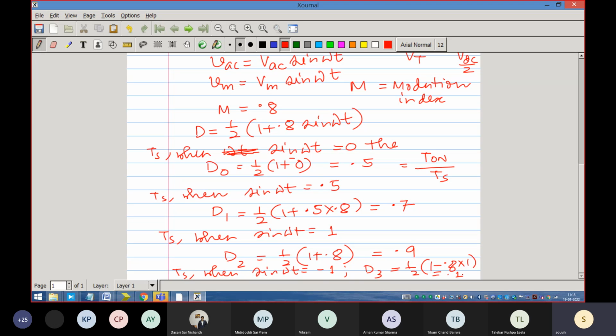So it is not surprising. You have to generate a continuously varying duty ratio function. That is what is given by this. This is what you are doing. You are producing a duty ratio just like a buck converter. If you remember the buck converter, it is like a buck converter with a varying duty ratio that you are producing in order to synthesize a sine wave.